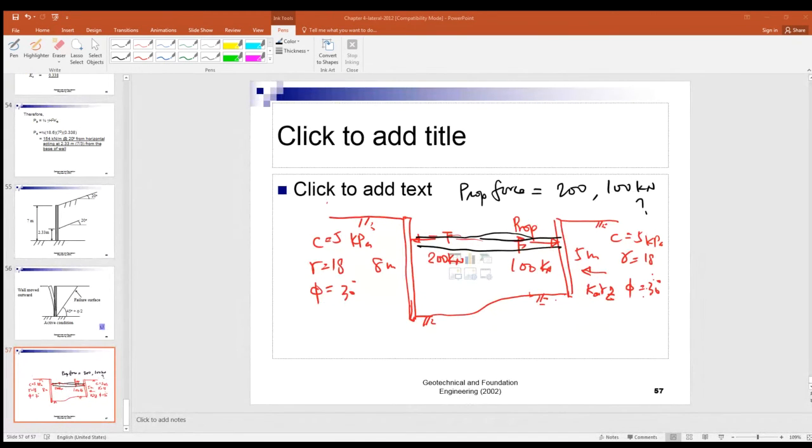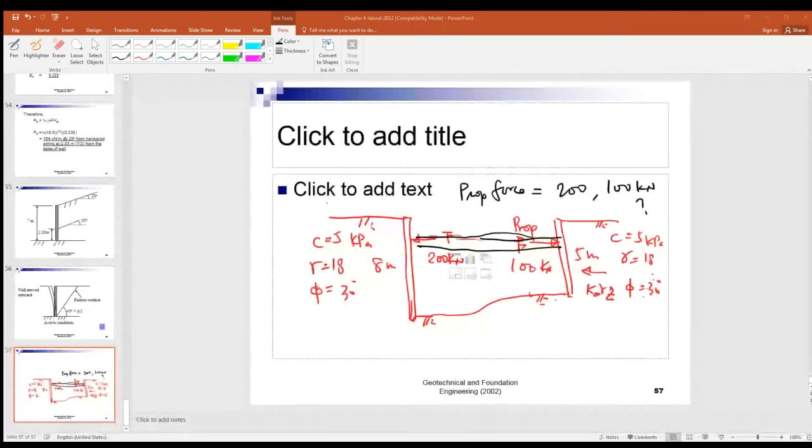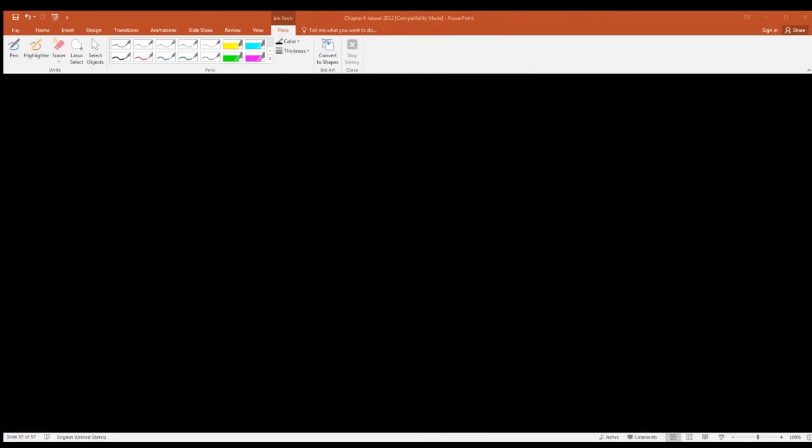Okay. So you got a cut there and fill there. Right? So you put this cut into the fill. So you balance the cut and fill. So you are trying to use the material there, right? You remove the material and then fill the other spots of the area with that material. So you balance the cut and fill. So that is quite a good and economical way to do that, right, in Hong Kong.